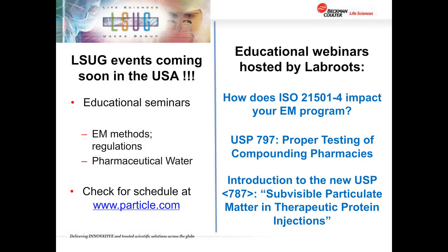But if it's a 21501-4 type test, you're looking for size definition. You're looking for verification of the volume sampled either by an airflow test plus time, because you're always reporting counts per volume, so you need to verify that. And then you also want to look at your counting efficiency at a couple of different sizes as specified in the document. Those would all be things that are critical to fulfilling a 21501-4 type